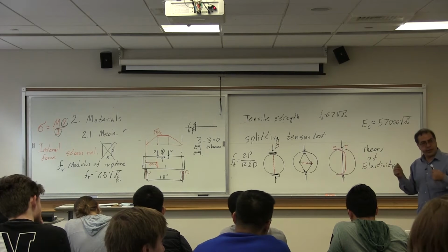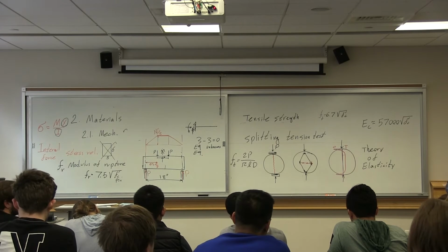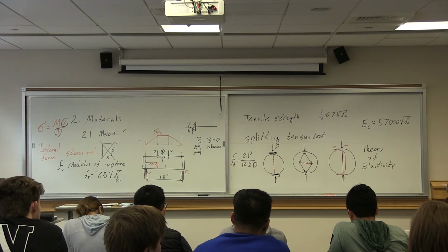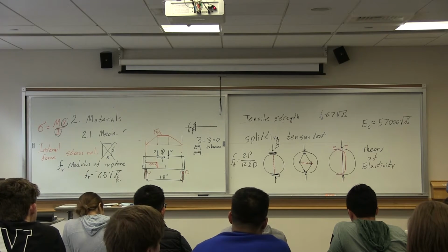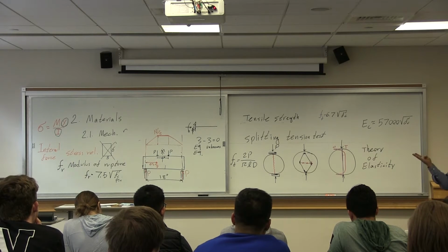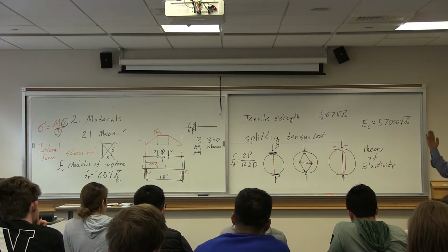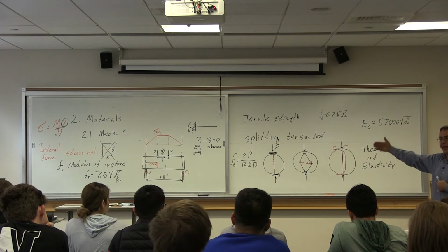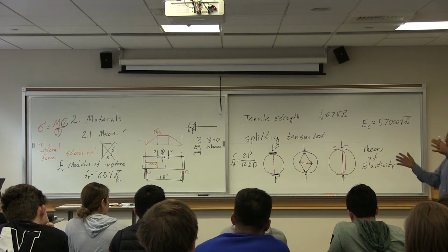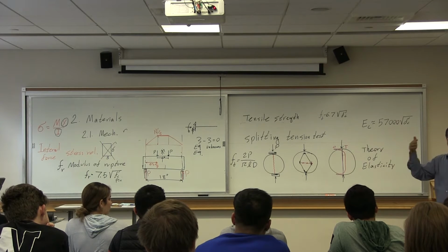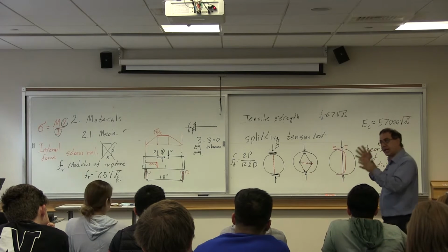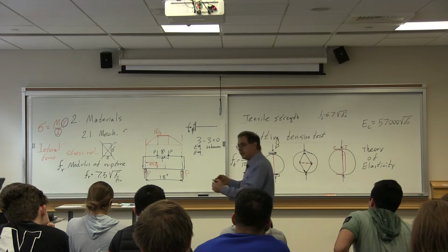How do you want to correct that statement? In 2D, 3 equations is correct. That means as long as the structure is on one plane, you have 3 equilibrium equations. If you are looking at 3-dimensional space, you have 6 equations. So that 3 is not exactly correct; you have to specialize it.